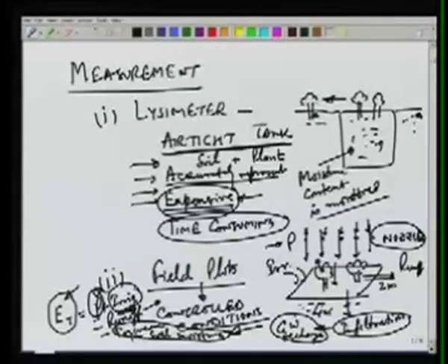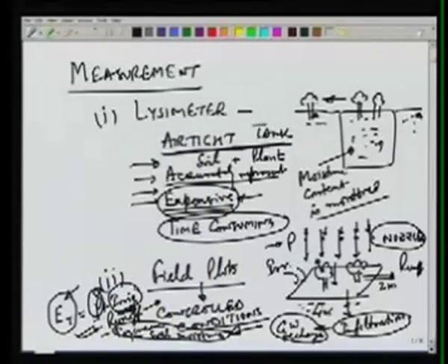Typically what we try to do is maintain the soil below the plot at the field capacity or below the field capacity, so that groundwater recharge is minimized, and therefore typically we will ignore this and use only these terms, precipitation, irrigation, runoff and soil moisture, which can be measured easily and evapotranspiration can be estimated.